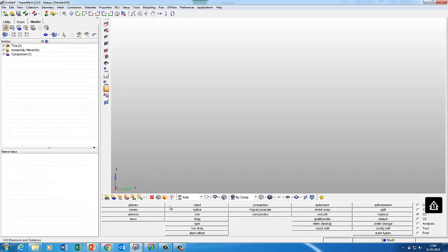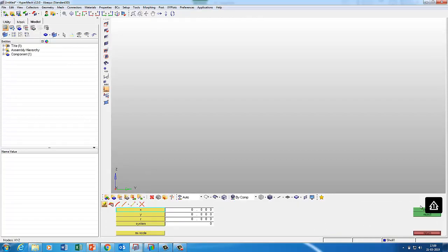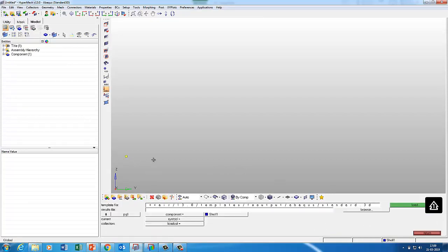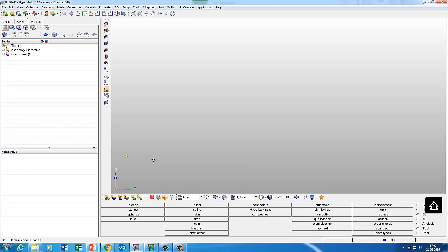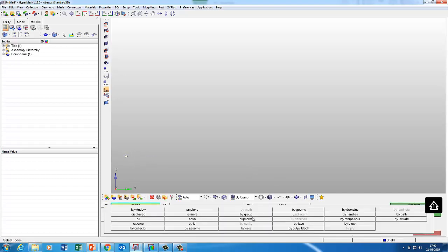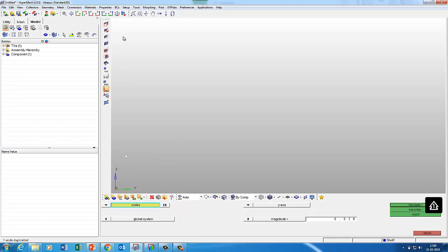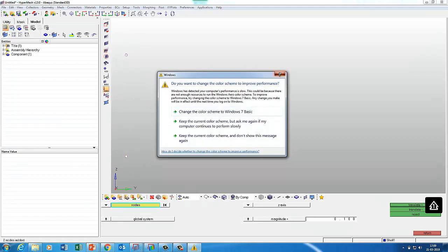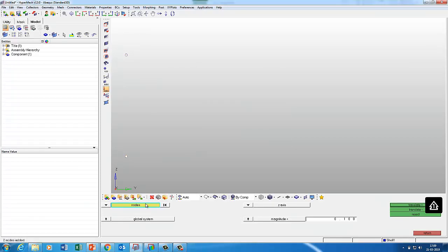So first I'll use the function F8 and put a node at 0 0, and then I'll press Shift F4 and copy the node. We just want a constant cross section, so I'm going to move it around 0.1. So this will be the height we have taken. It is immaterial; we just want a constant cross section and to measure the heat going through the composite.